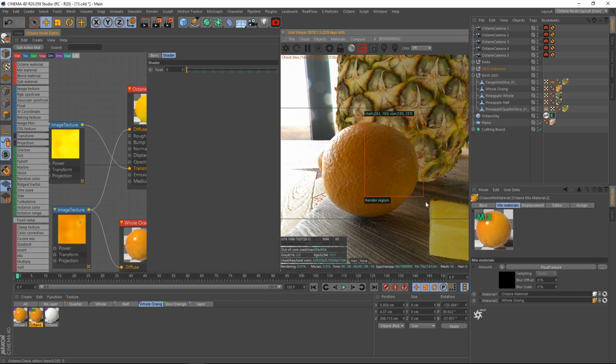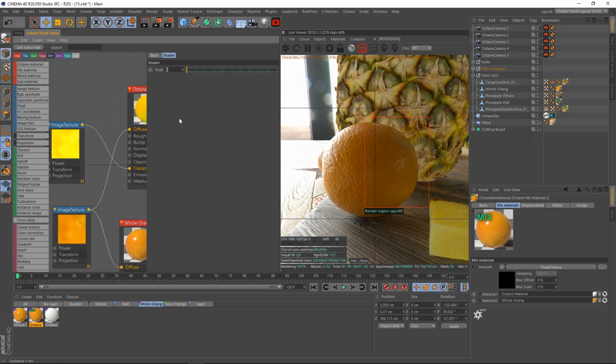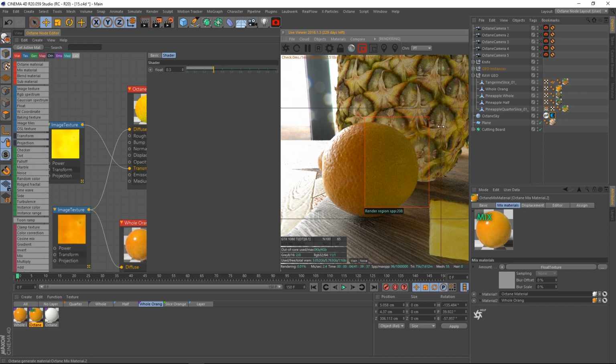We're going to go ahead and grab a render region real quick. Let's compare this here. We have that. We'll just do compare, store render buffer, and now let's just drop this or bring this up to 0.3. And I'm thinking with a value of 0.3, it's going to take a little bit, but this is going to add, 0.3 might be too much, but once it starts churning through, you can see the fill on the shadow of this is night and day. Like, look how much more we're going from that to that. And as this fills through and gets more reflections, more life, it's going to look better and better.